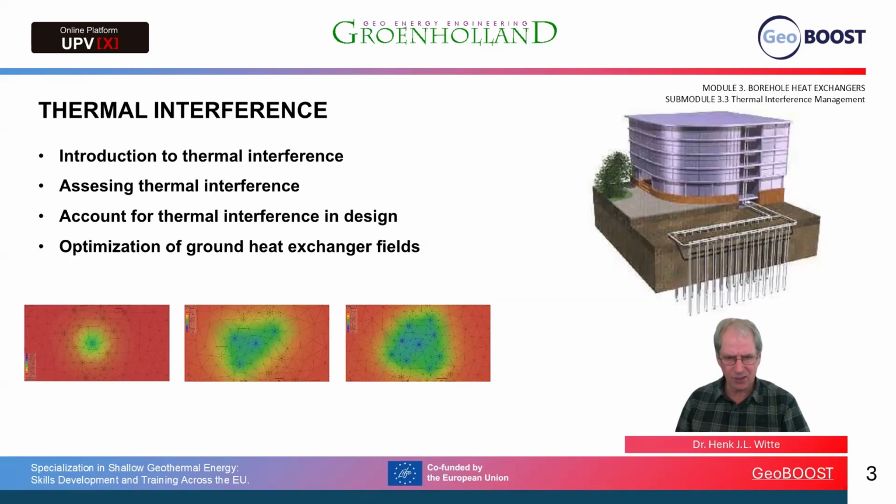And this is different in collective systems where they are hydraulically coupled and the temperatures even out, but the heat extraction rate is less for a heat exchanger in the center than for a heat exchanger at the edge. But in individual systems that we often have in practice, the actual temperatures of the systems depend on the relative location.